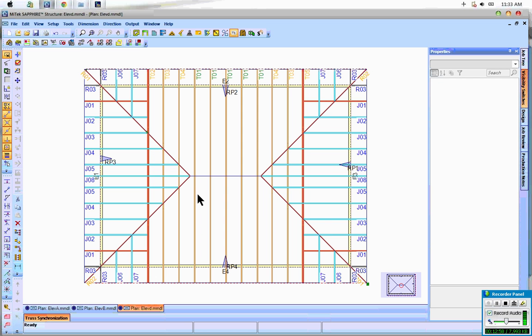That's kind of an overview of the project file, some settings that are critical to that working for you, how to create one truss that's shared across multiple elevations effectively, how to make a PCL file and use that file to bring in trusses to a specific set elevation.